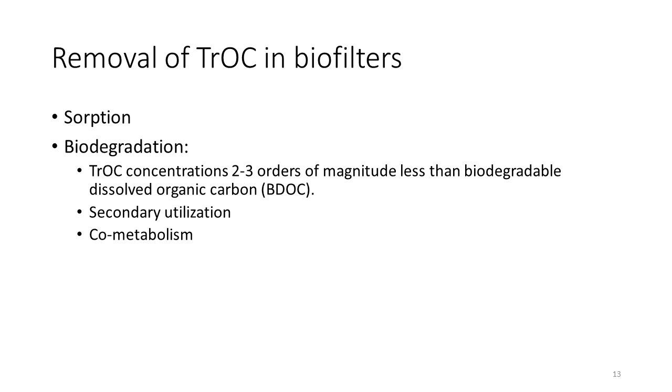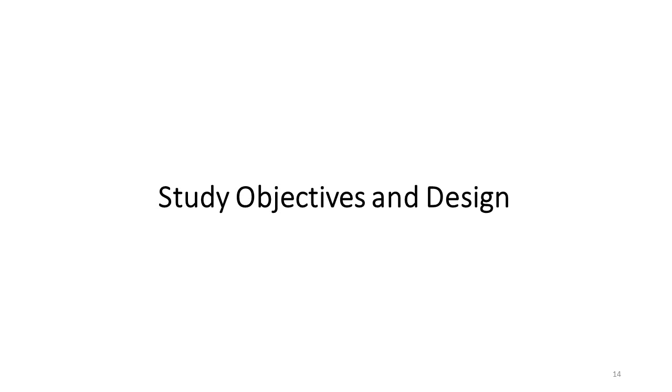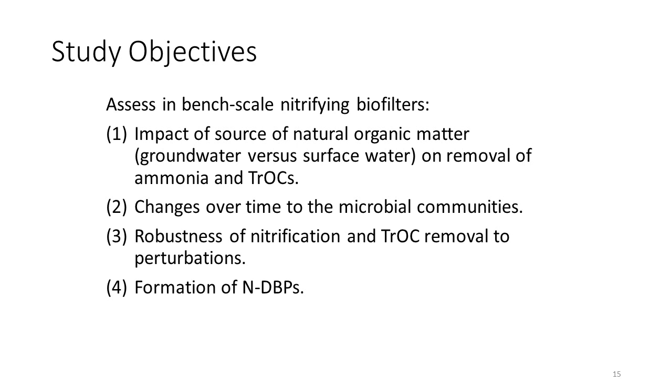It's important to note that the concentration of trace organics is 2 to 3 orders of magnitude less than the BDOC in the water. So the organisms are not using this as their primary source for growth. It's either through secondary utilization or through co-metabolism, which is just fortuitous reactions: the enzymes happen to be around, and you just knock into the compounds and degrade them. Okay, so onto our study objectives and design.